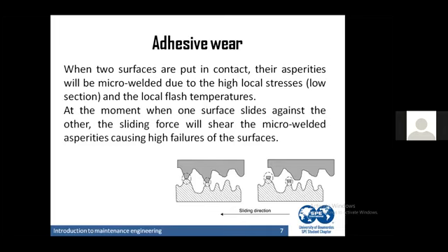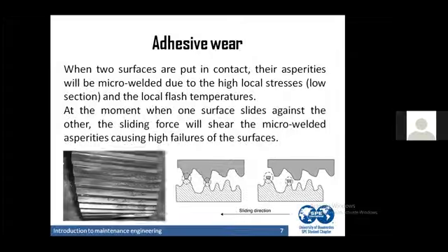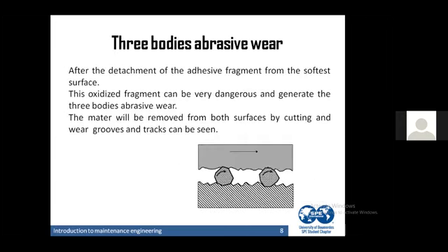Now, when those two surfaces are sliding against each other, the sliding force will shear this micro-welding, and the asperities will be sheared, causing the failure of the surface. In this shear, we can see this mode of wear, which is the adhesive wear. We can see high pitch due to the adhesive, to the shearing force. When we shear,